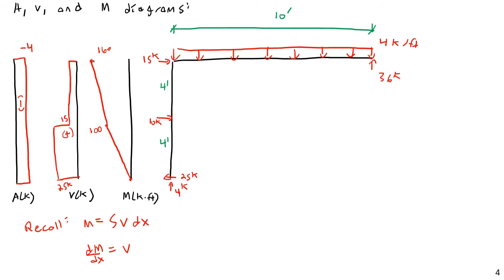Okay, and then the end force, not the end force, sorry, the end moment that's being transferred through the joint will then drop this back down to 0. So your shear and bending moment diagram should always find their way back to 0. Okay, questions on that? Yes?